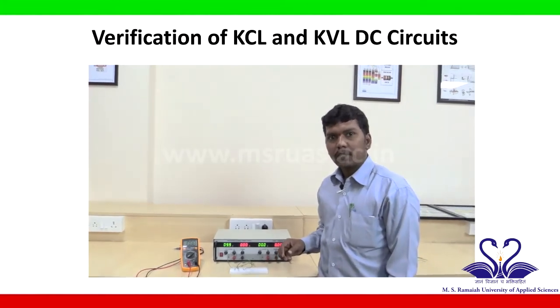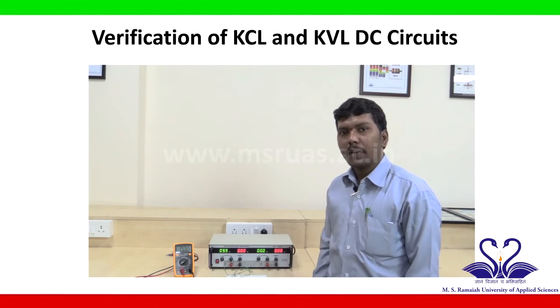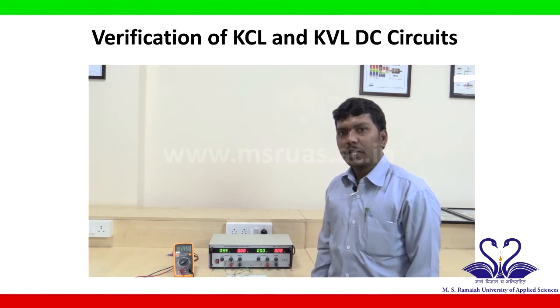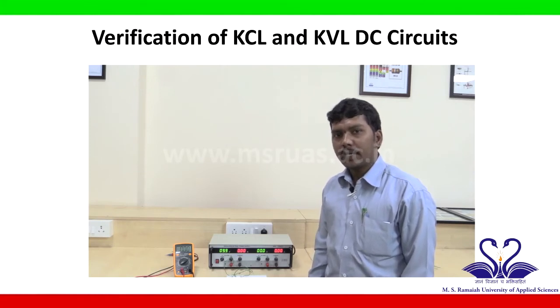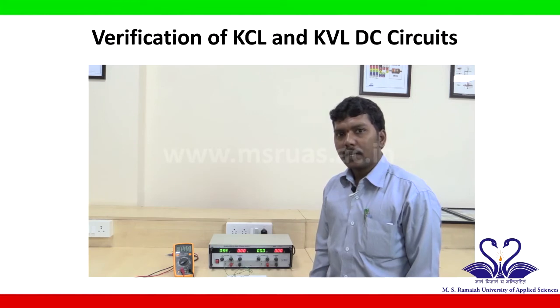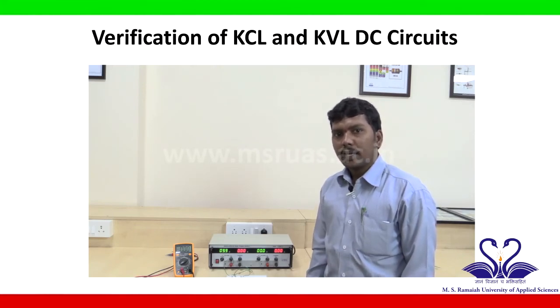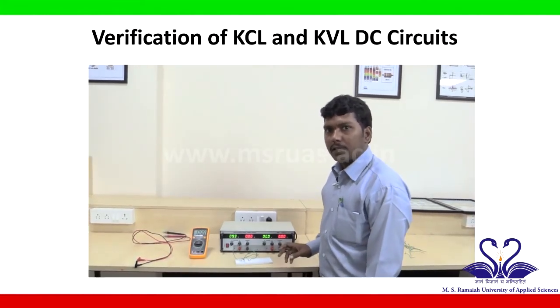So from the given circuit it can be seen that I1 is equal to sum of I2 plus I3. So according to the given values, I1 is 3.05 milliamperes, I2 is 2.25 milliamperes, and I3 is 0.79 milliamperes. So according to the statement of Kirchhoff current law, the sum of incoming currents is equal to sum of outgoing currents. That is nothing but I1 is equal to I2 plus I3. Hence KCL is verified. Let us verify Kirchhoff voltage law, that is KVL.